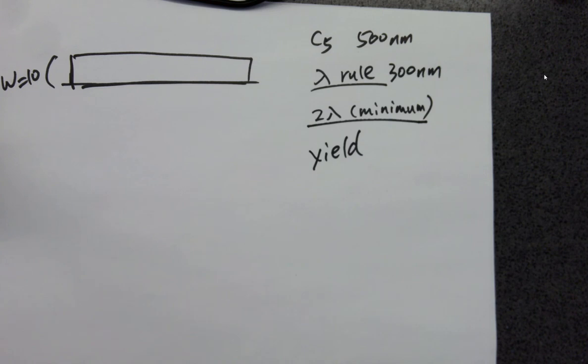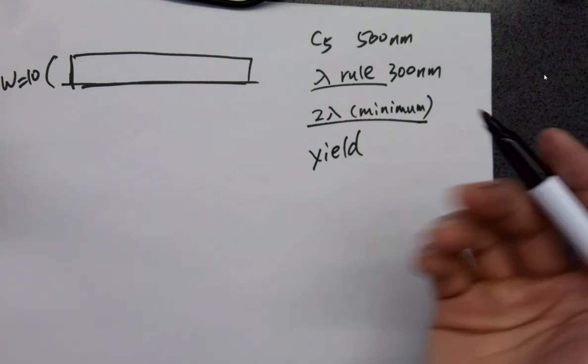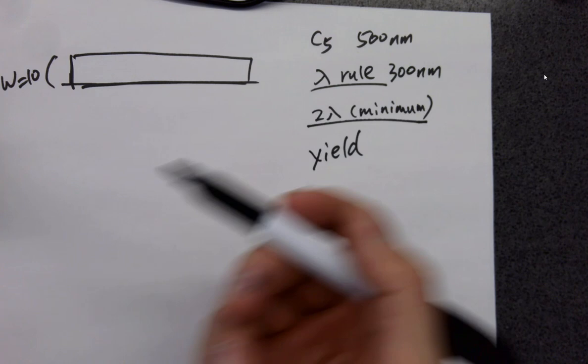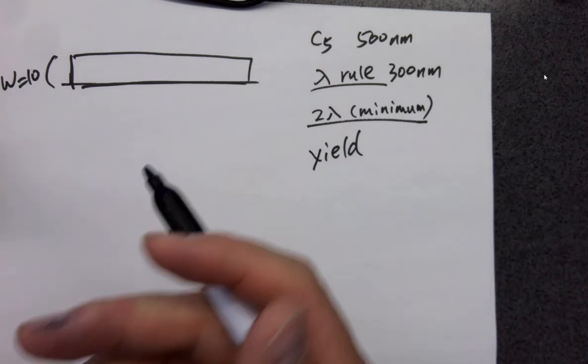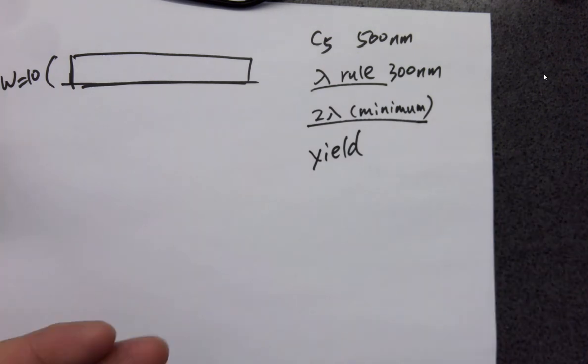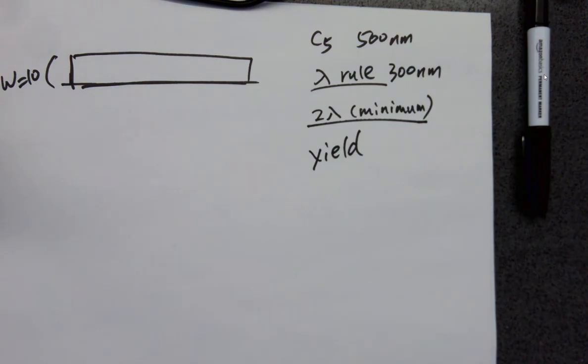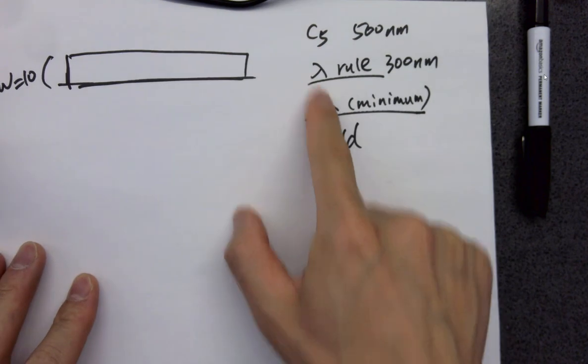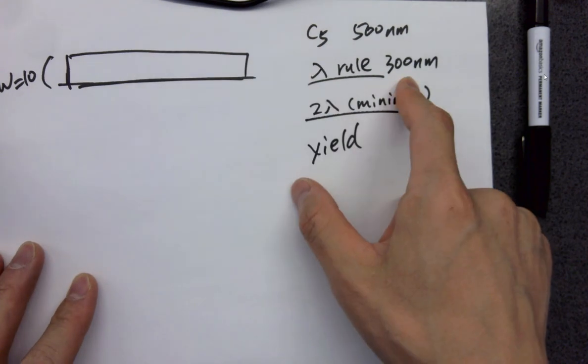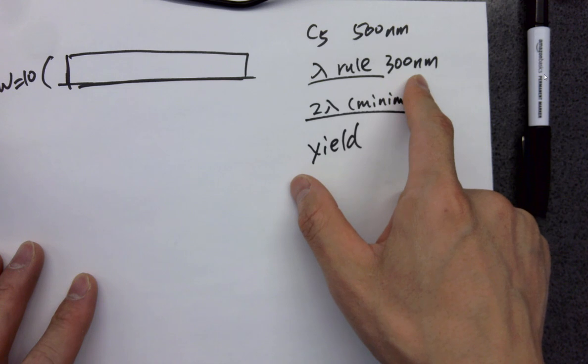But not always everywhere, because lambda is the minimum unit. There won't be like 0.5 lambda, but it's usually larger than lambda. So there will be several other rules defining the space between metal 1s, metal 2s, between metal 1, 2, poly, all these kind of things, and we'll talk about them later.